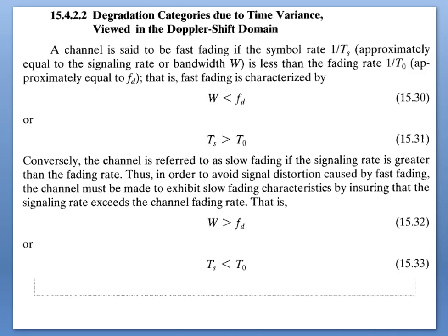Owing to vehicle motion, at time T1 the specular phasor has rotated through an angle theta, while the net phasor has rotated through an angle phi, which is about 4 times greater than theta. The rate of change of phase near that time is about 4 times that of the specular Doppler alone. Therefore, the instantaneous frequency shift d phi by d theta would be 4 times the specular frequency shift.